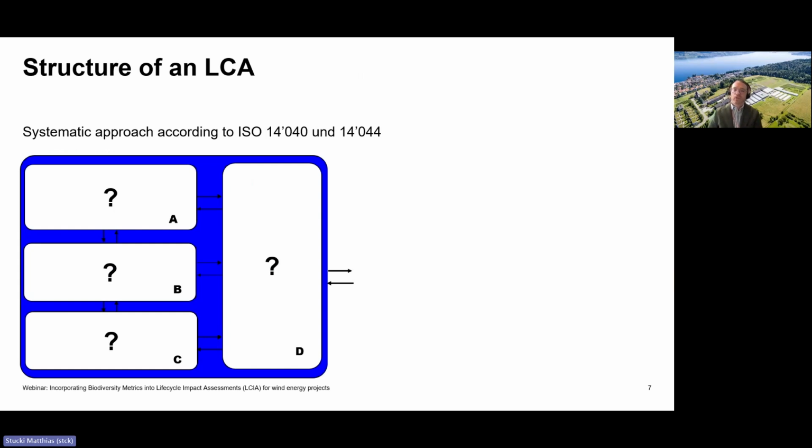When we also look at what we can see in the ISO standards is that every LCA should have these 4 steps covered. The very first one being goal and scope definition. Then the second step in every LCA is the life cycle inventory analysis. This is the step where we gather all the data that we require to do an LCA, where we put the data together in one large model, typically in an LCA software, where we model the whole product system.